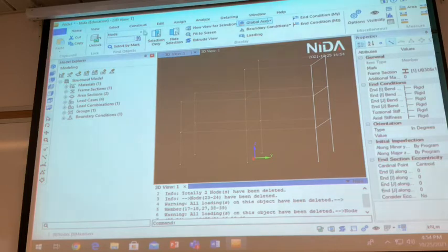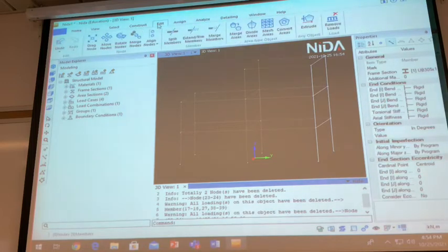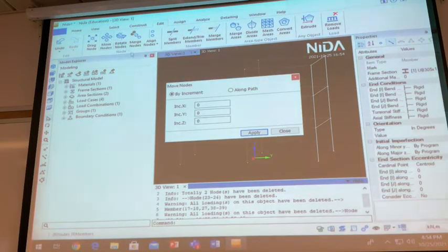Okay. First, if you want to revise your model, normally you should go to edit, and then under edit you find move loop. According to the global axis, it tells you I want to move the loop this way, in Y. So this is my input. I should put 2. This is in this way, so this is positive 2 in this way.